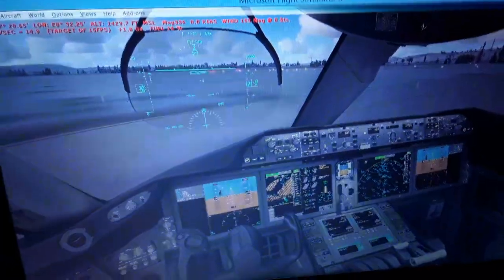So you can see also, as I told you, the airports where they are located, the VOR stations, the ADFs, the NDBs. We have the navigation aids, the nav aids, the waypoints which are horizontal and vertical navigation fixes for the aircraft. We're going to have to fly through some waypoints when we're flying. We're going to select them using the flight management computer, so I will show you also how to do that.